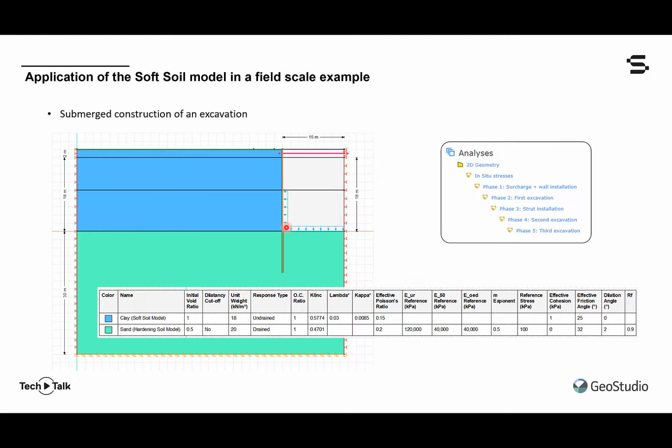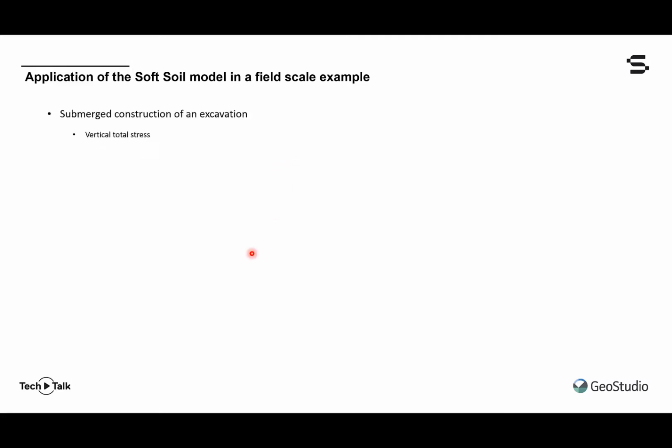So in other words, Sigma by default removes all material, the total stresses, from an excavation. And so, since it is submerged in water, always at 2 meters below original ground, we have to put that water back via a hydrostatic pressure boundary condition. And so I'll let you explore exactly how that was done. It is quite intuitive. You can explore that in the actual project file on our website.